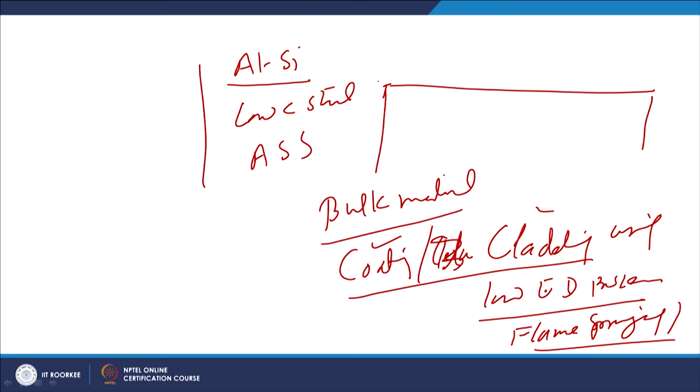Apart from the coarse grain structure in flame sprayed coatings, we will see some pores and some inclusions. So, pores in the form of gas pockets, and inclusions will also be there due to the interaction of the metal with the atmospheric gases. So, these kinds of things will be leading to the presence of inclusions here and there. Sometimes even poor bonding is observed.